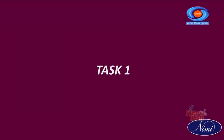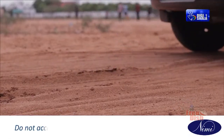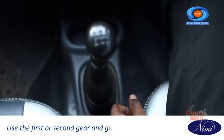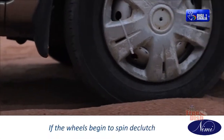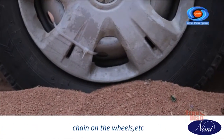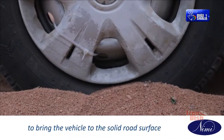Task 1. Driving a vehicle through sandy road. Do not accelerate much, otherwise the wheels will spin. Use the first or second gear and give sufficient acceleration. If the wheels begin to spin, declutch and switch off the engine, then use any of the techniques like chain on the wheels, etc. to bring the vehicle to the solid road surface.